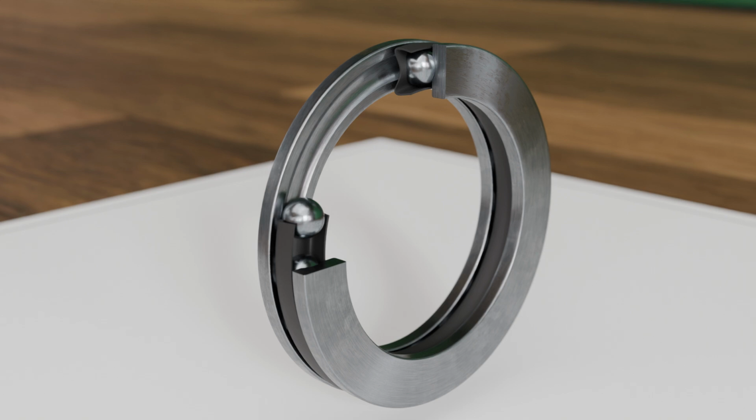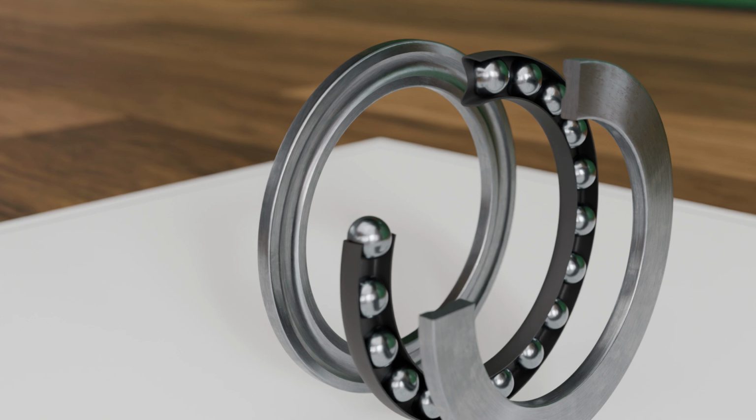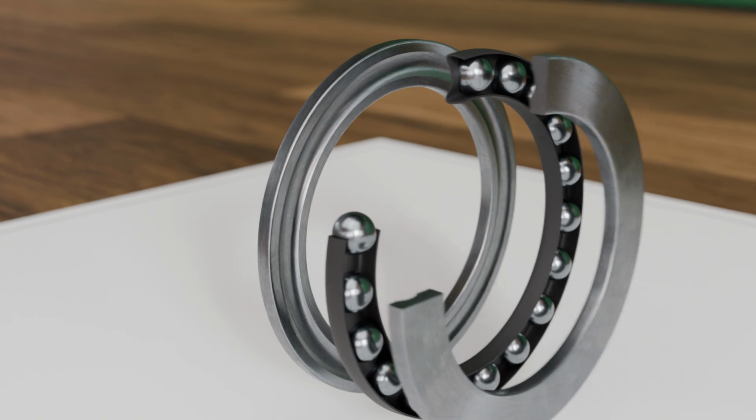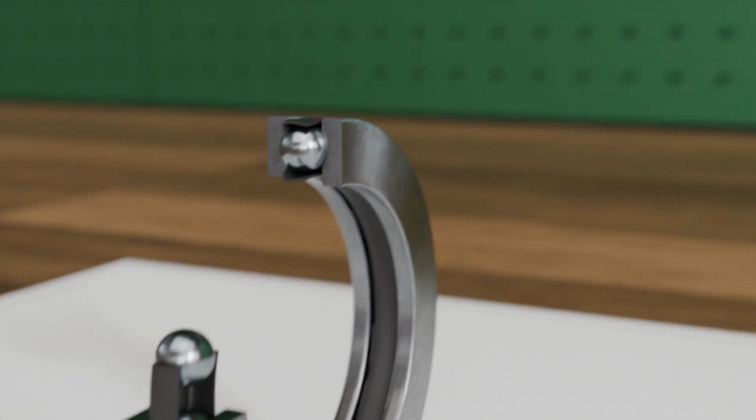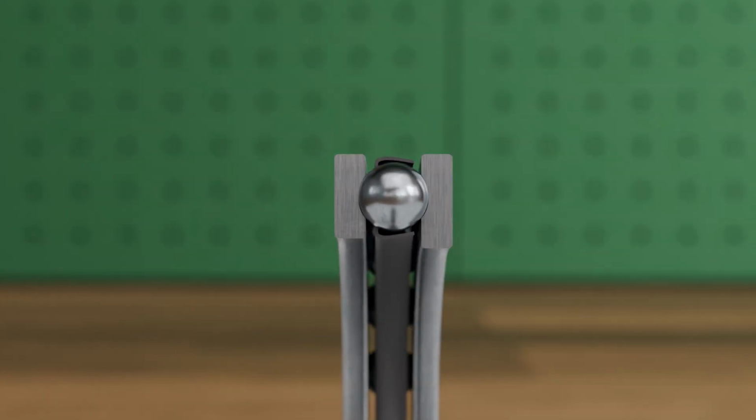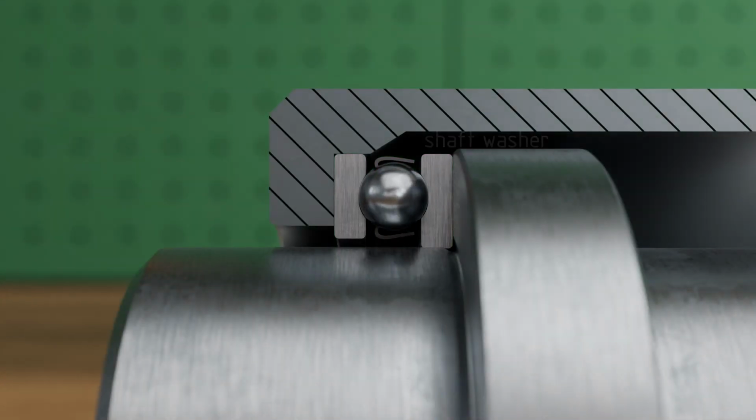Single-direction thrust ball bearings are designed to absorb axial forces in one direction and usually consist of a cage with a ball set and 2 raceways. They are non-self-retaining bearings, so individual bearing components can be easily replaced, which simplifies assembly. However, since there is no fixation in the radial direction, these bearings are not suitable for absorbing radial forces. The 2 raceways of a thrust ball bearing differ in bore diameter. The raceway that fits onto the shaft, called the shaft washer, has a smaller bore than the opposing housing washer.